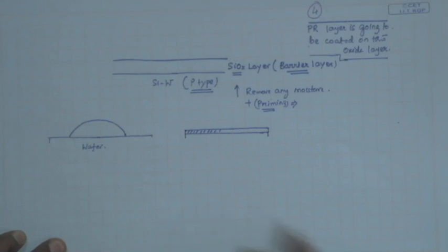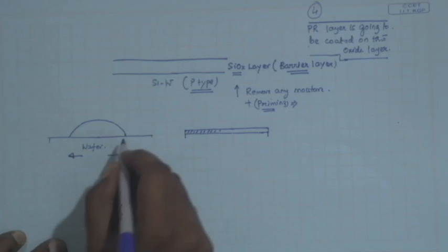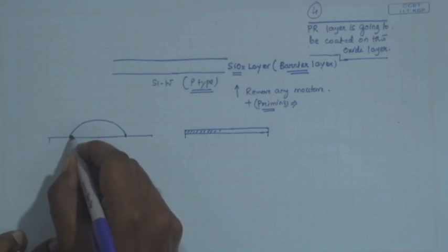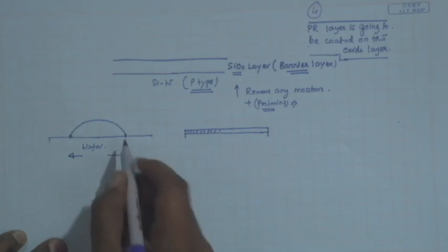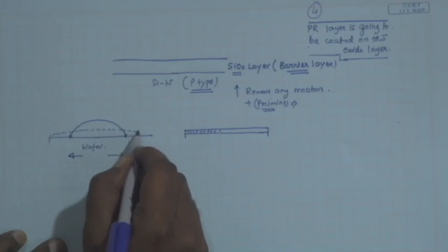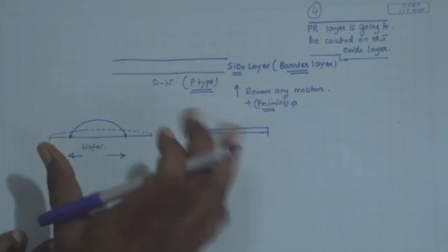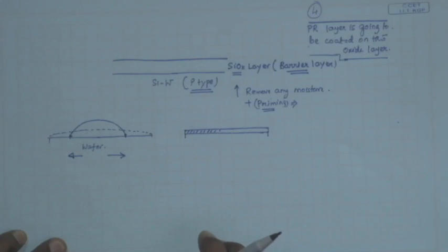How do you do that? You need to apply some force to overcome the balance in the horizontal components of the surface tension along the contact line, and that is conveniently done by applying rotation, which in the form of centripetal force spreads the initially dispensed solution drop. But several additional things also happen.